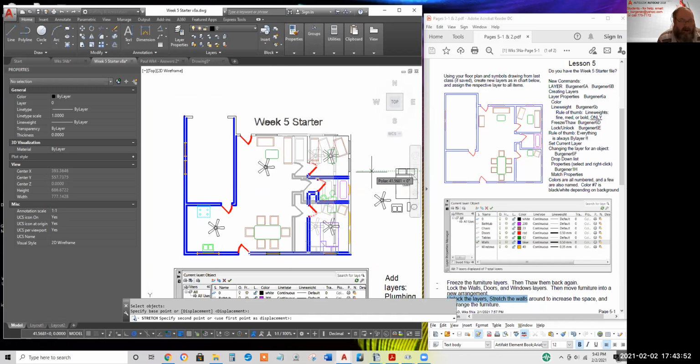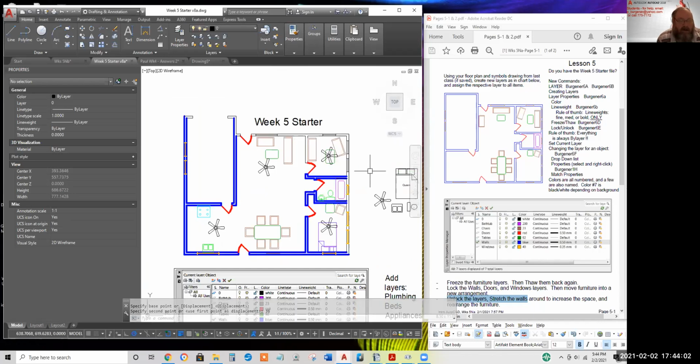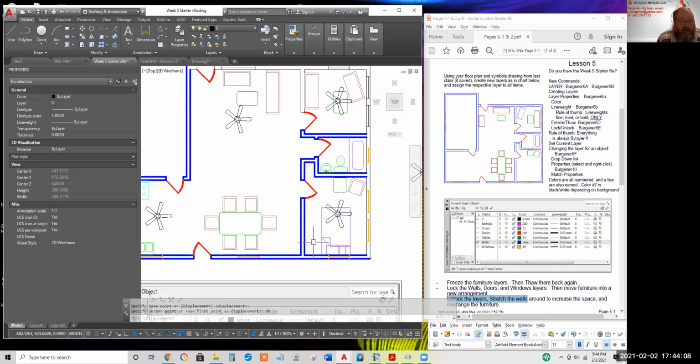Okay, this drawing's been converted to an AutoCAD unit, represents an inch. So if I want to stretch it 3 feet, I got to type 36 to stretch. Maybe make this bedroom a little bigger. I'm going to try a lasso. Got to be a, there we go. Go in the right direction. And pull it out, say 24 inches.